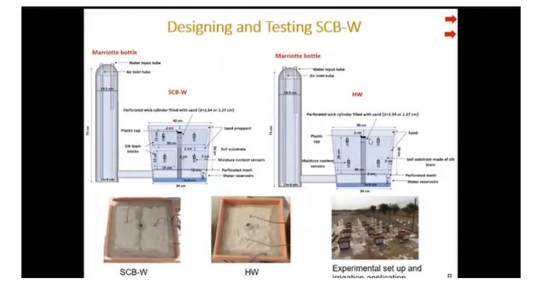In my master thesis, I used HYDRUS to do some modeling. I conducted an experiment where we designed a soil structure called the smart capillary barrier, which consists of a finer soil texture in a block shape, surrounded by sand. This structure creates a 3D capillary barrier that reduces evaporation losses from the soil and stores water in the soil, so you maintain more water content. You don't lose the water very quickly due to evaporation.